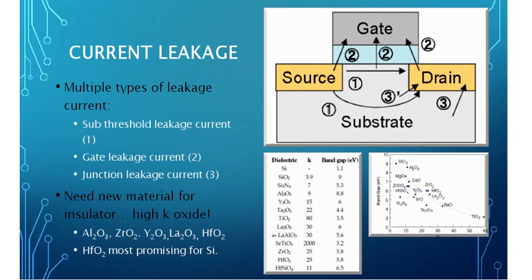So what the semiconductor industry did was they started going with higher K oxides with regards to the gate leakage, because as this thinned, this became more prevalent. And so they had to cut this size down in order to keep the scaling going. And you can see here how the higher K oxides, typically zirconium dioxide, hafnium oxide, tend to have a higher K than the traditional silicon dioxide, but they have a lower band gap.